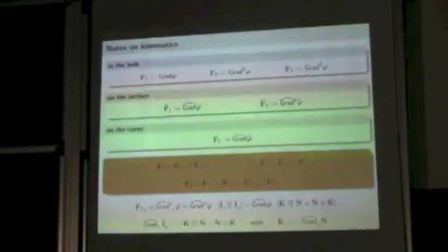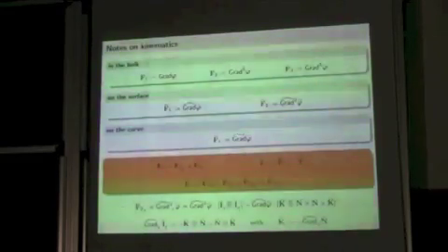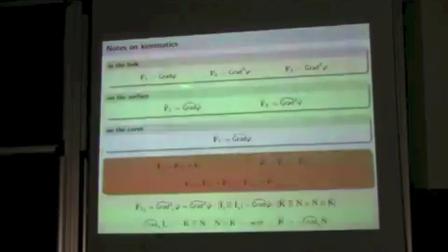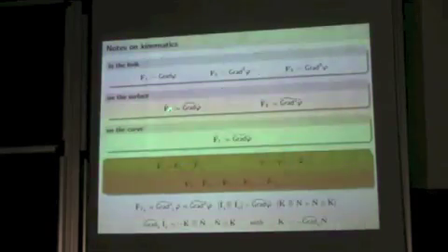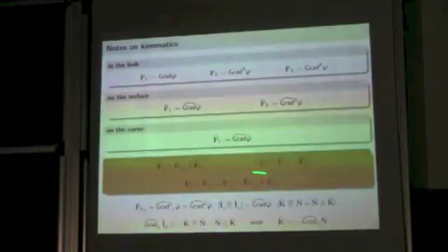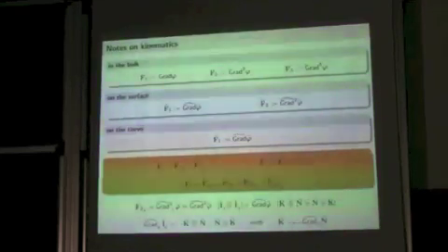This is exactly the way this theory actually boils down to the Steigmann-Ogden theory. In fact, if you do the calculation, you would see that if you allow the bulk energy to be only depending on F1, so if you have a first order bulk material, you could only have a tangential part of the surface gradient. So you could only have F hat 1 tangential, and you could only have F hat 2 purely tangential. But still, this F hat 2 purely tangential has curvature in it and has normal in it. What we want to do is to look into these additional parts, the normal parts. So it simplifies to Steigmann-Ogden theory, but it's more general.